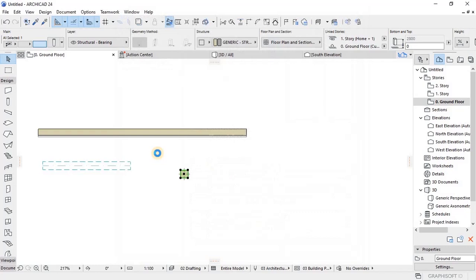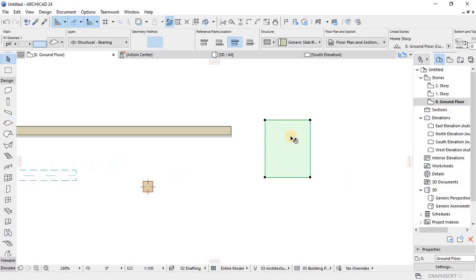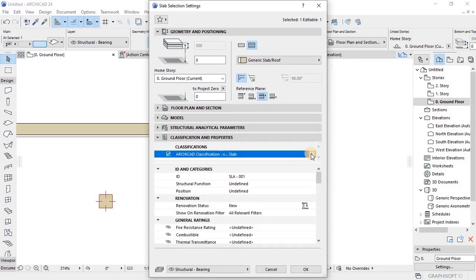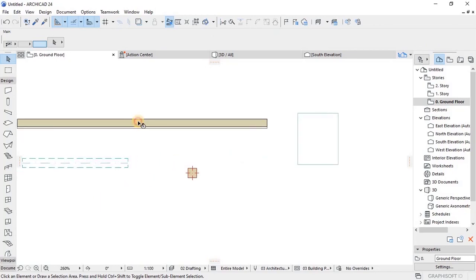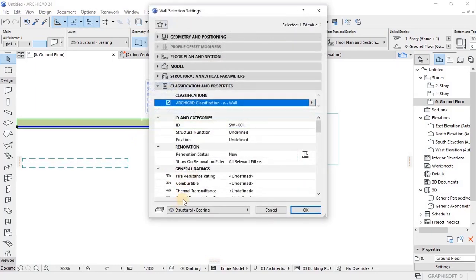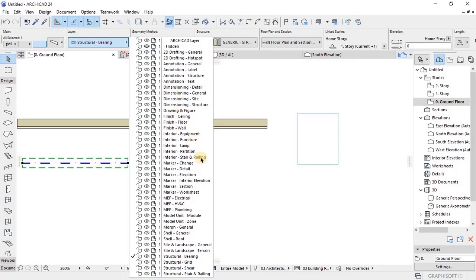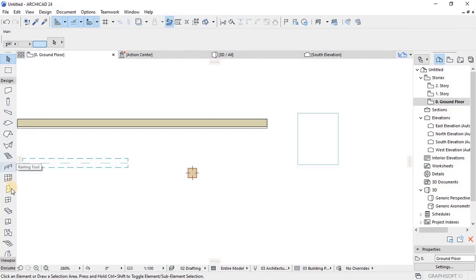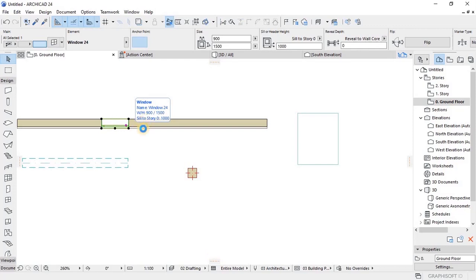So Archicad properties are used to add optional descriptive data to building elements. Like here, I'm working with beams, columns. I'm just showcasing on a simple template, the descriptive part of the element. So it comes up with a basic classification system. So the systems are solely for the construction industry. We have standards, versions that are out there. There's the Uniclass 2010 version, 2020 versions, and then the ones which was developed by NBS, Uniformat, stuff like that.